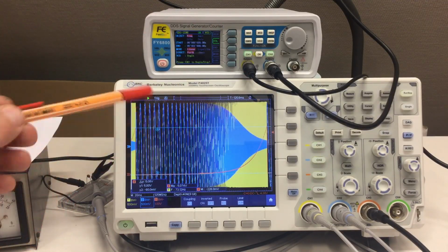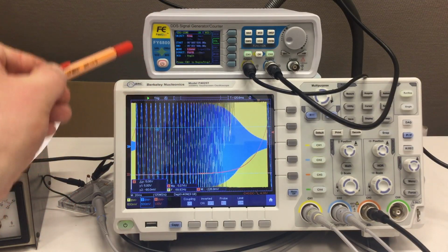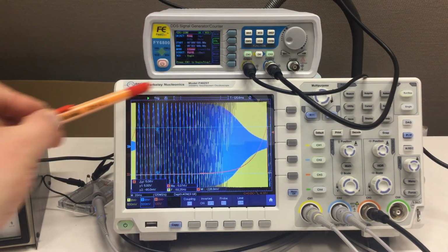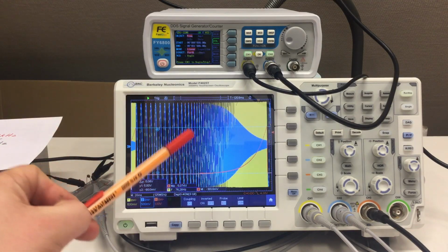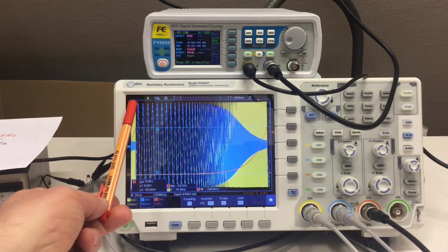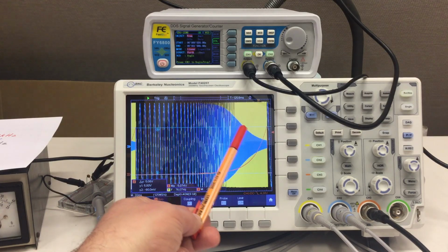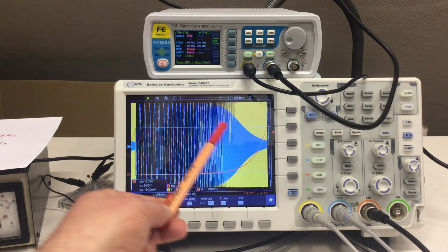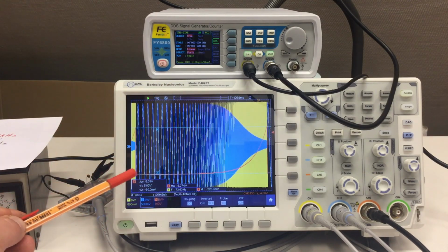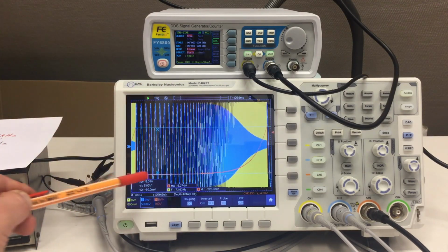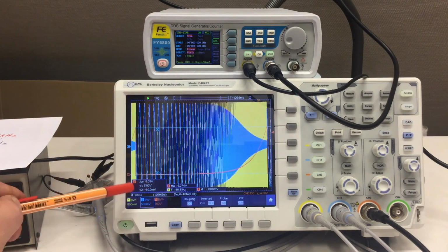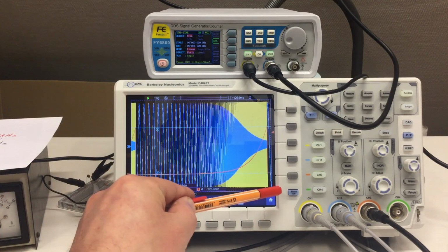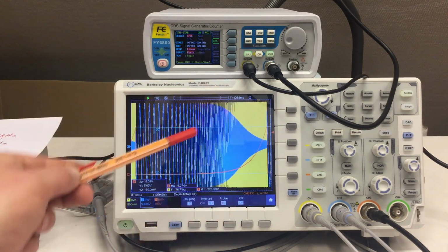The good news is we managed to sync the frequency sweep done with our function generator using a VCO with our oscilloscope, and we get some live Bode plot like curve, at least the amplitude curve. And we were able to do this in a logarithmic frequency scale at the bottom, and we were also able to do it in a linear frequency scale at the bottom.